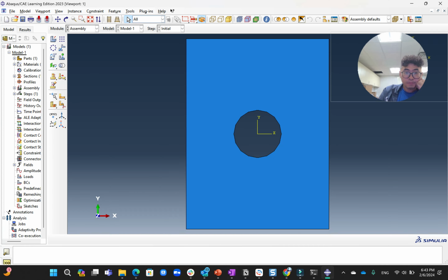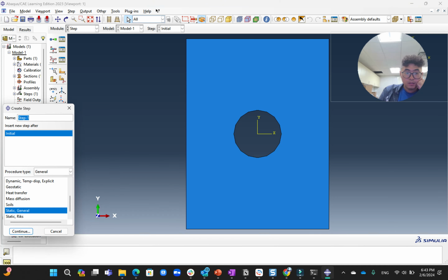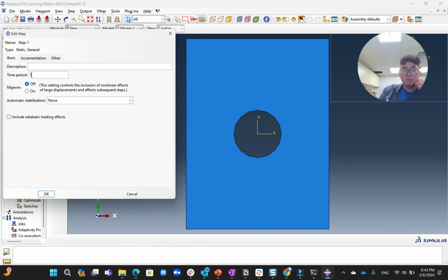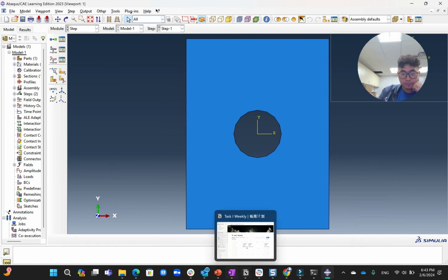And here, step. You need to create a step. The static general is the default one. The time period is one. Actually, this time period is not real time, it's just the simulation time, so it's one.